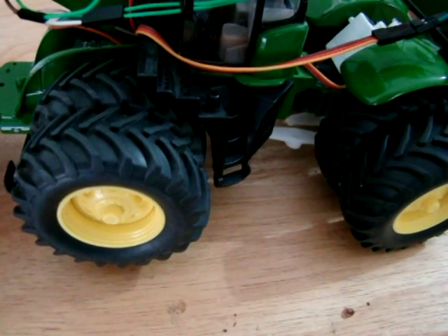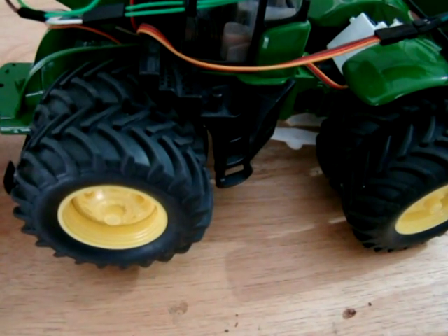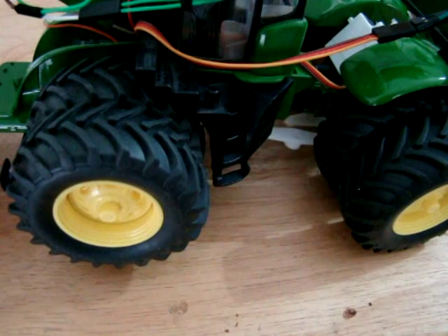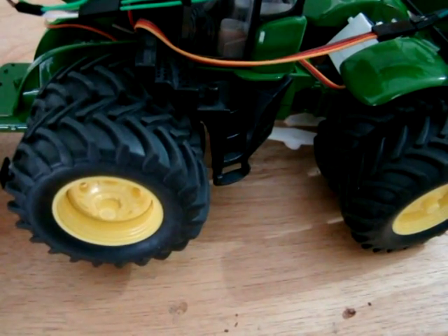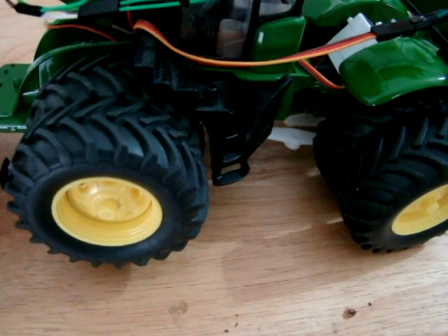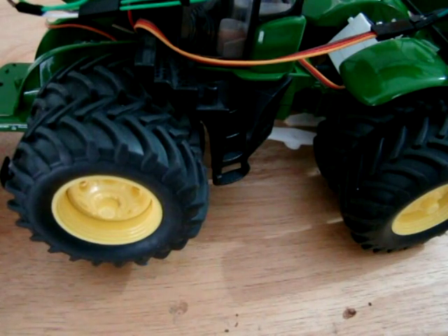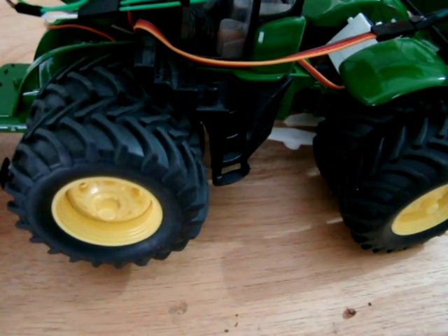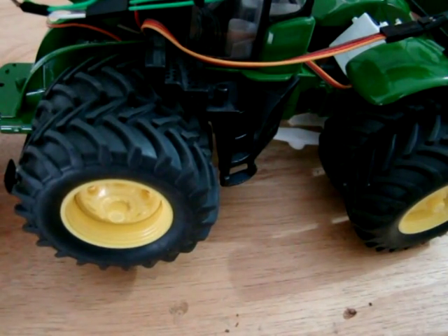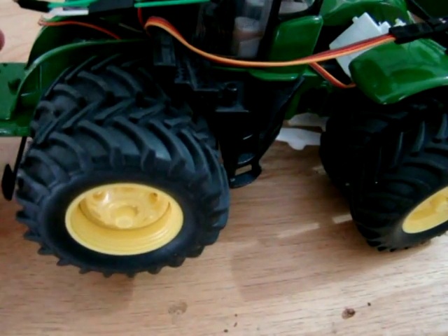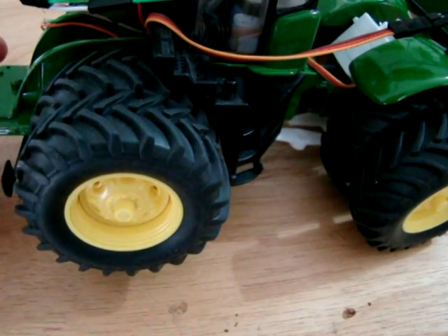Okay, so now we want to test out our drive motor. So we open XCTU again, go to the terminal, create the packet. It's going to be 0A, 4A, 44, 39, 52 for my tractor again, same as before. And this time the command is 01 for the motor. So the first command I've sent here is a value of 99. That's around about the center value, because our range is from 0 to 255, and 99 in hex is close enough to the center, so the motor's not moving now.